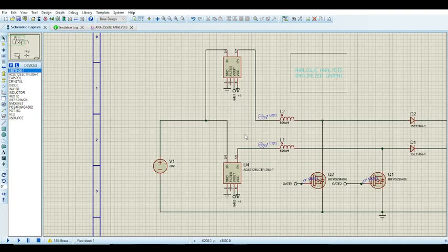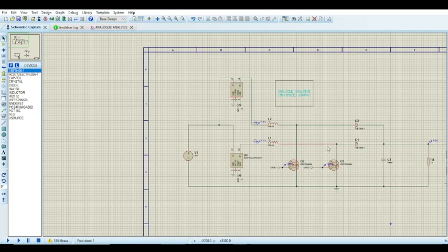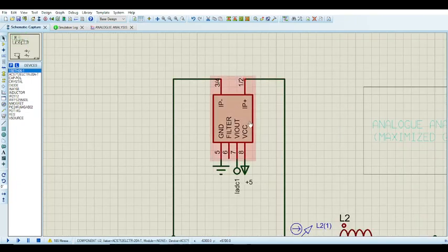Current sensor. You have to use a Hall effect current sensor for this. But if efficiency is not such a big concern, like let's say you're okay with shaving off 0.05% of that efficiency, or in some cases 0.5%, then you should use a shunt current resistor.